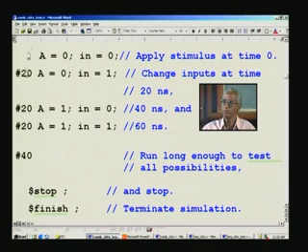On the other hand, if you do not put any timing, all this will be processed simultaneously, because we are dealing with hardware. In C, what will happen? You go statement by statement, and there will be a delay from one statement to the next, no matter how many gigahertz you have. It will take a finite number of cycles and go to the next only after it has processed one statement. So, it is sequential, all the microprocessors, DSPs, right. In contrast to that, FPGAs and ASICs are all concurrent, no matter how many thousands of statements you may have here.